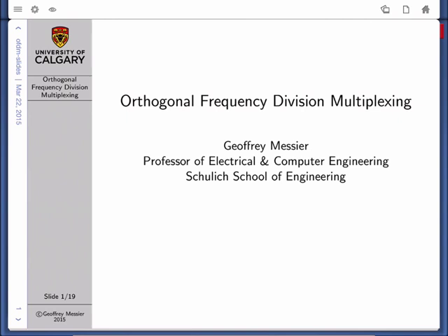Another example is a wired channel where there is not a perfect power match between the impedance of the cable and the impedance of the receiver. So this often happens, for example, with digital subscriber line or DSL modems. When there's an impedance mismatch, there is energy reflected back from the receiver that bounces back and forth on the cable and results in multiple reflected copies of the received signal. And traditionally, equalizers have been used to deal with dispersive channels.